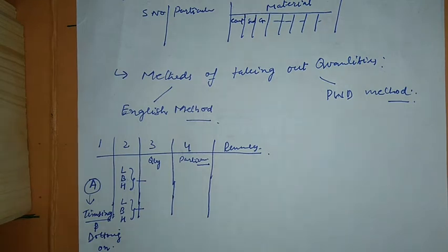It often happens that an item which has already been written occurs a number of times. Instead of repeating the dimensions, it should be multiplied, or it is timesed. So this is what I mean by timesing. Similarly, dotting on means if we have to add the similar measurements, then we use the method of dotting on.